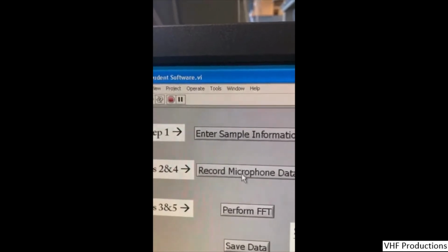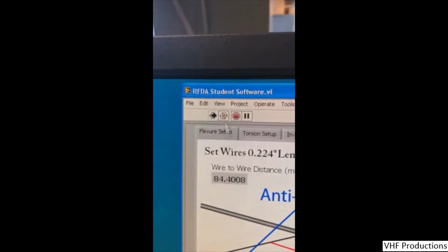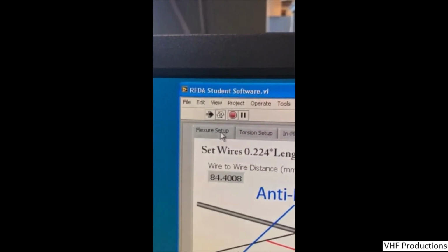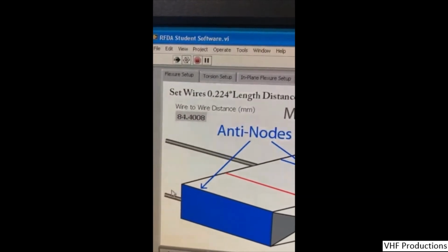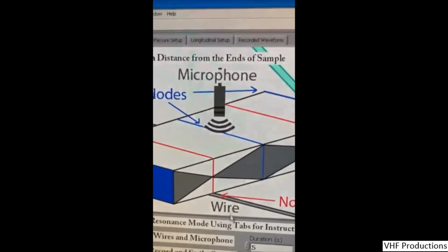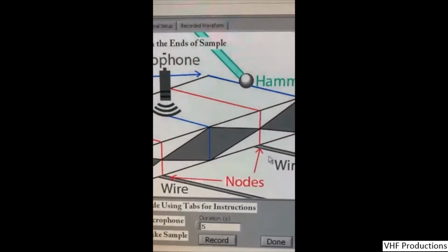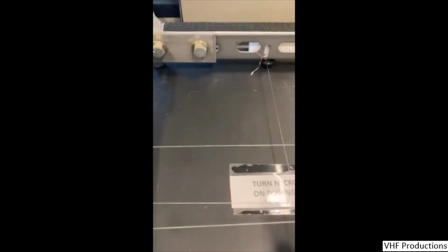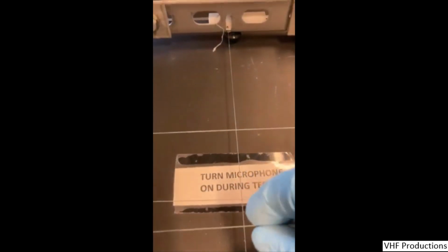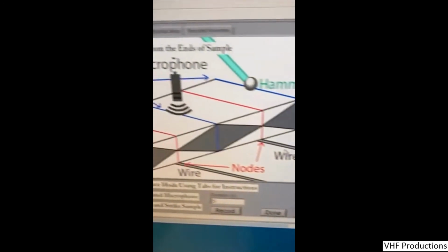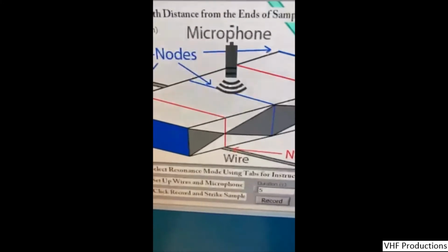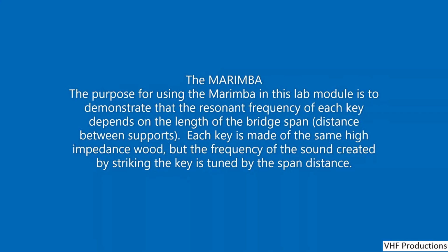Following the measurement of the elastic modulus, we can take the data and examine the window of the frequency obtained and determine the decay function corresponding to the reducing amplitude of that signal as a function of time from that decay signal. We can then extract the decay half-time. In addition, we can obtain the frequency range of the peak, defined as the full width at half maximum value of the peak, and use that measurement of the minimum and maximum frequencies on either side of the resonant frequency, and use that data later to calculate the Q factor.